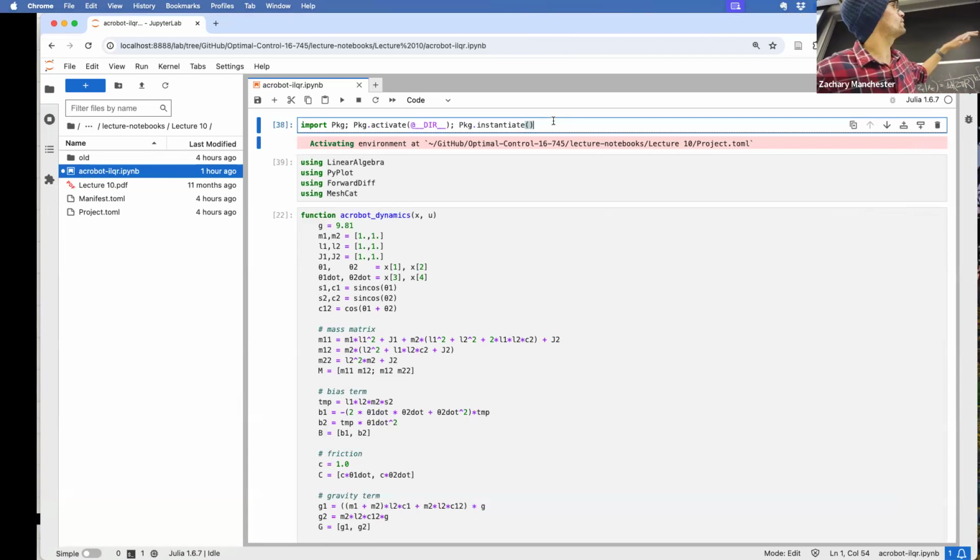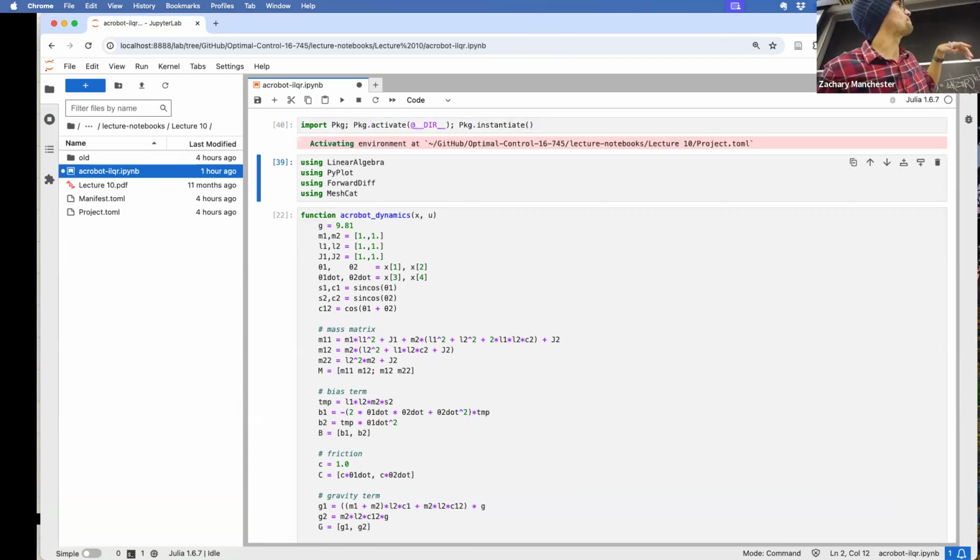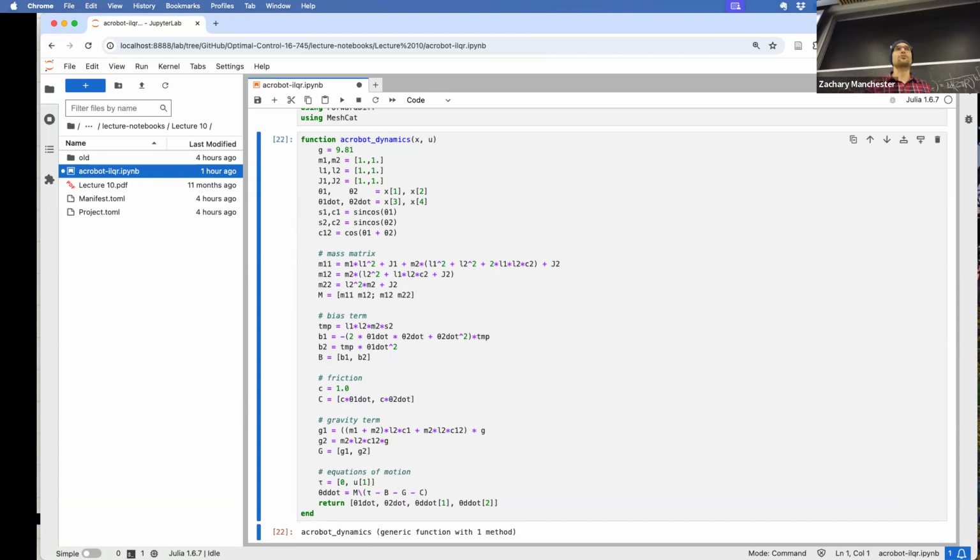Okay, before we leave, let's do this on something fun. Has anyone heard of an acrobot? Has anyone heard of a double pendulum? Okay, acrobot is a double pendulum with a motor at the elbow joint. So it's got a passive shoulder and only one motor. So it's 2 degrees of freedom, only one motor. The reason it's called an acrobot is it's used as an approximation of an acrobat swinging on a trapeze, where you can bend your waist to swing, but you can't really exert torque with your wrists. So it's an approximate acrobat kind of vibe. That's why it's called the acrobot.